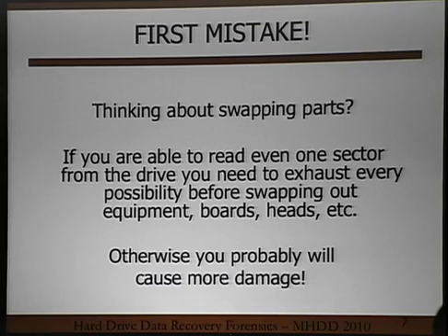Even with boards, you have to be very careful about buying an identical drive and then swapping the board. I know I've said that in some previous events, but some newer things have come out lately that can cause damage with the boards. And in certain drives like Western Digital's, you may need to unsolder a chip and move it. It may not do damage if you swap the board, but it's not going to work either. So you need to know that. I want to make sure that if you're thinking about swapping parts, you know when we actually discuss that, and where we're actually going to talk about practicing with the drive.